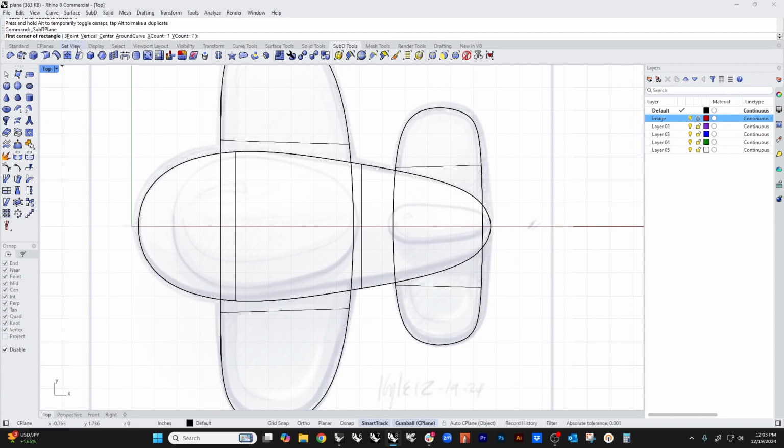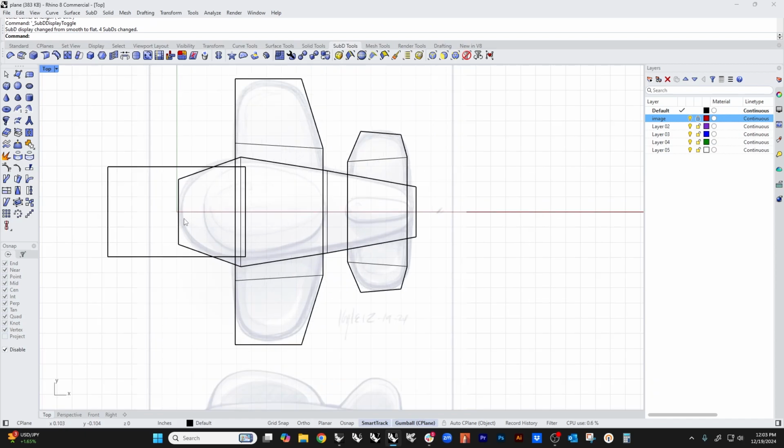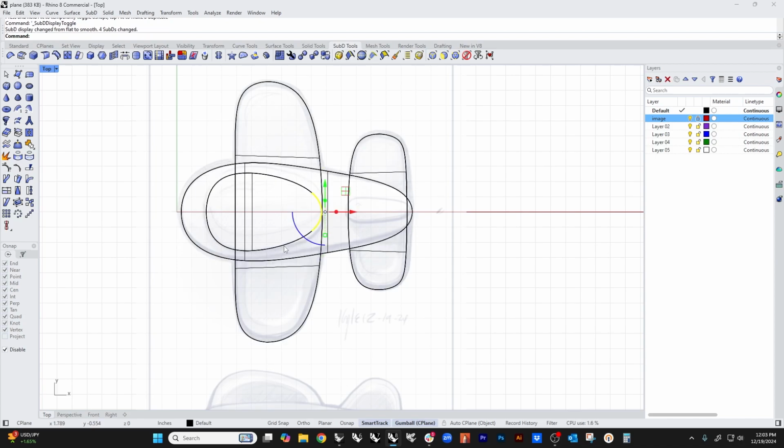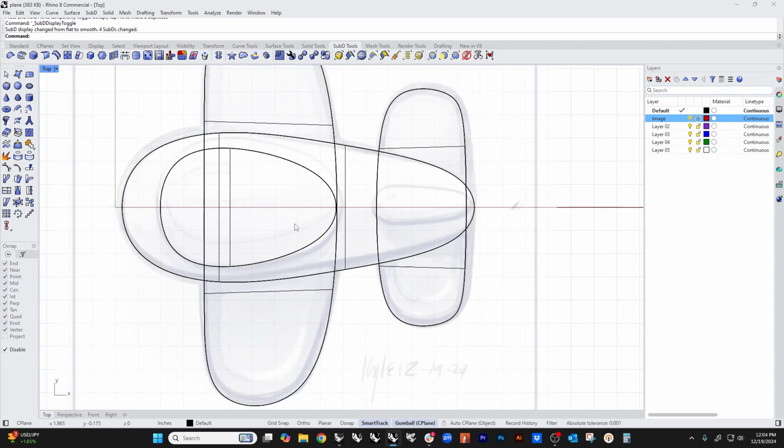Same thing. We're going to do the exact same thing. Put it at the center, and I just like sticking it at 0 so I know that it's dead centered. And I'm going to pull one out that's kind of the width of our canopy. And then I'm going to Control-Shift-drag, stick that there, take advantage of the fact that it's already selected. And then I'm going to Control-Shift-click, extrude, scale, and then flip it into box mode and just double check and see how it looks.